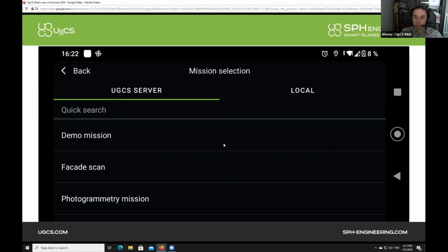And what is important also is that together with the route, for example, when you save routes from the desktop application to the mobile application in your office before leaving to the field, you store not only the trajectory for the drone, you also store the elevation information. So in the field, all the relative altitudes will be calculated properly.